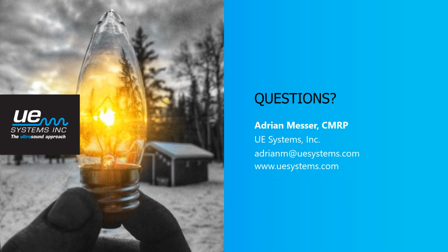So Adrian, a couple people asked about slow speed bearings and what the minimum RPM is for ultrasound to pick up those defects. So maybe you could answer that. Yeah, I thought about that. Normally when I'm talking about slow speed bearings, I'll mention that. But typically with UE systems, we refer to slow speed bearings as anything below 100 RPM, even into single digits.